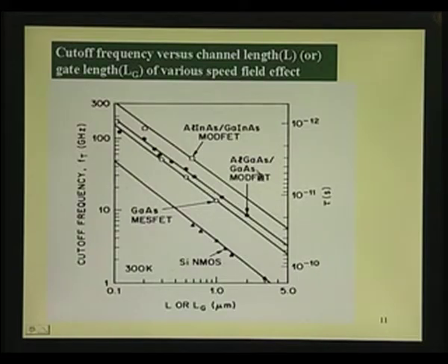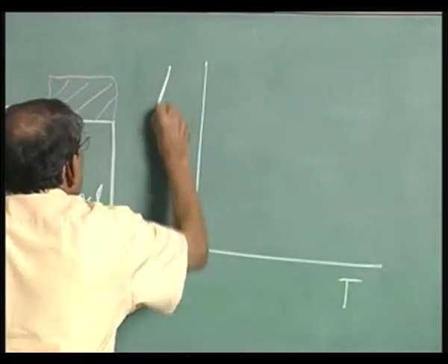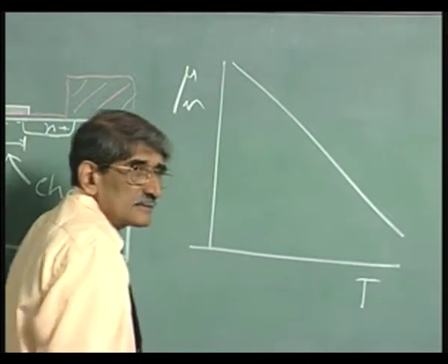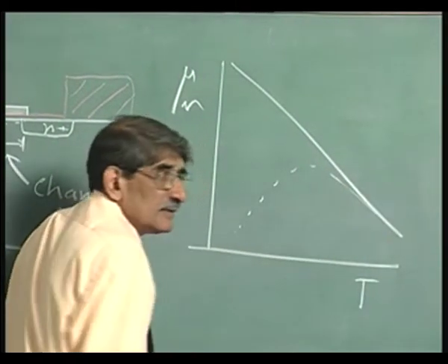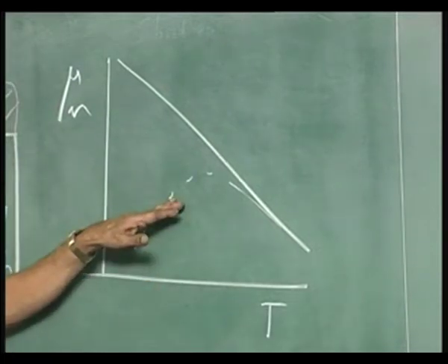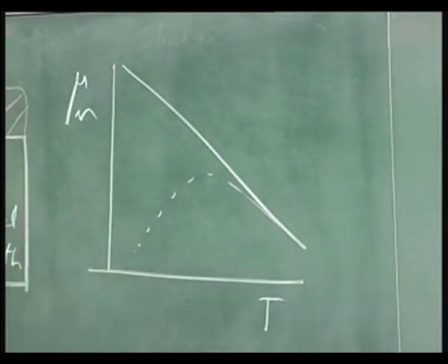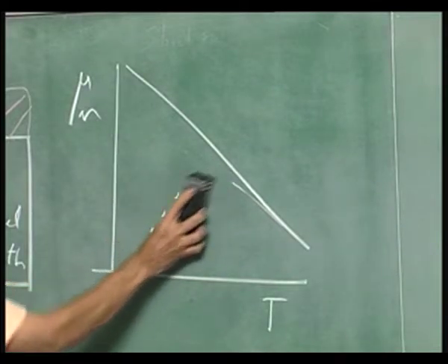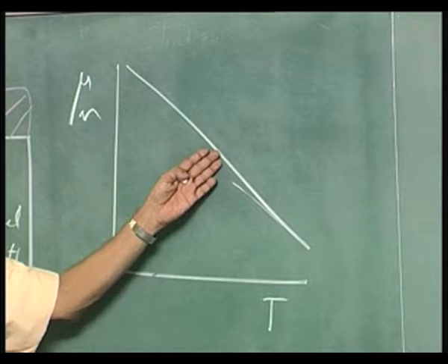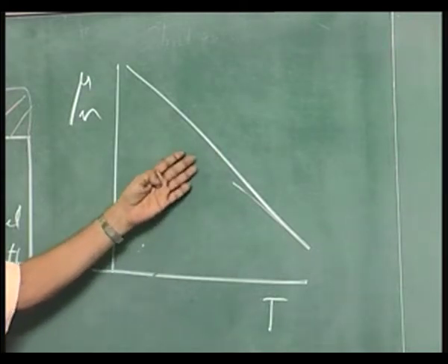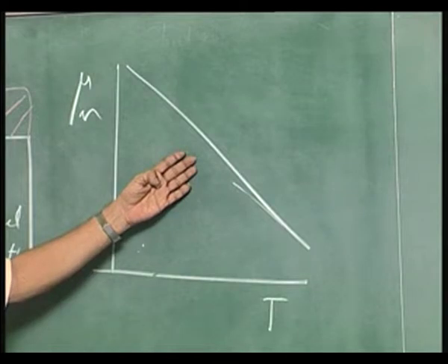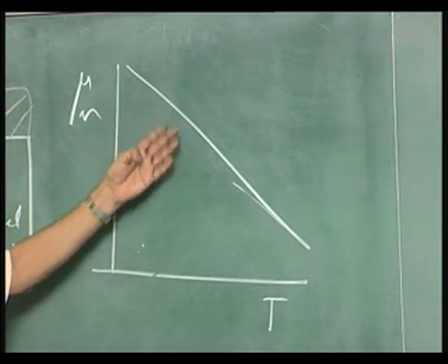And here if you go to lower temperatures, you can get this curve up even further, because if you remember we plotted the temperature versus mobility like that, and you had this curve here. I am removing that. That is the lattice scattering mobility. By separating the donor from the electrons, then the whole thing is like this. If I go down to temperature, you will not believe the mobilities of thousands, tens of thousands; you can get from 1000 or 100,000 if you go to liquid nitrogen temperature.